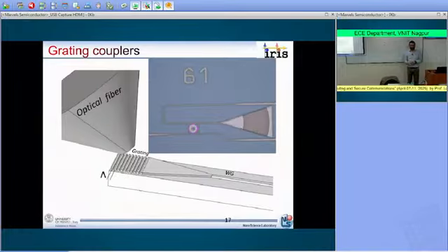Exactly. The first is the tapering. So here we have an adiabatic tapering. So the mode from there goes to here without any loss of power. Instead here, the mode is so large that all the power will be lost. But the second point is that you see that here the lines of the grating are not vertical, but they are curved. Why?